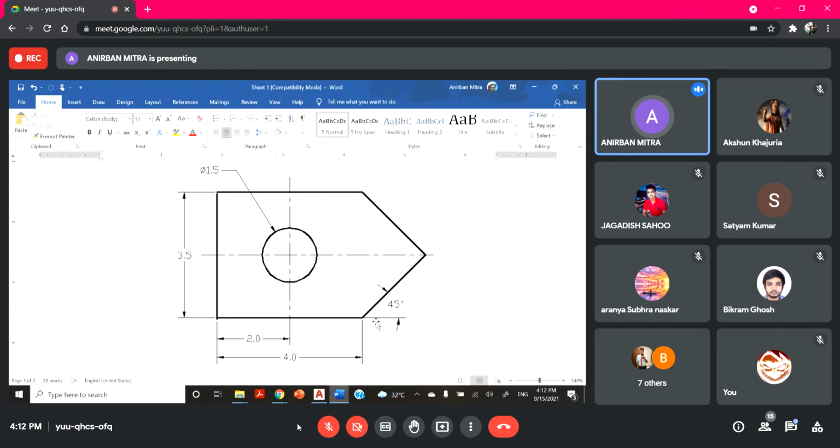After that I will share with you two pre-recorded videos, and in those videos I will discuss the layers option, where you can control the different properties associated with different lines, such as the line thickness or the line color or line type. Sir, you have previously shown how to change the line width. Yes, that is one option, but the more systematic option would be to go for layers.